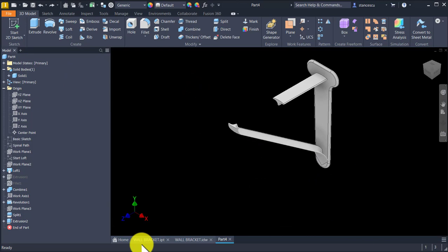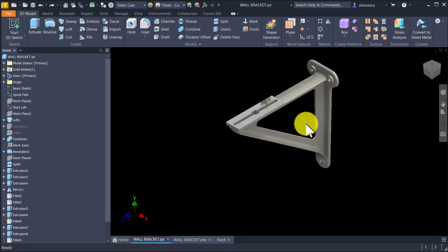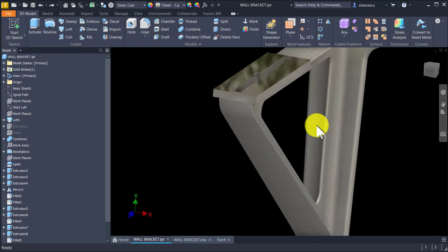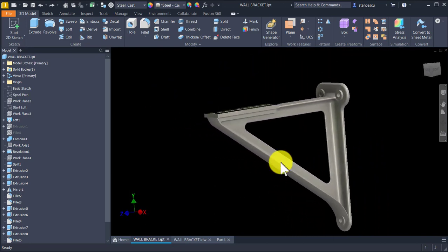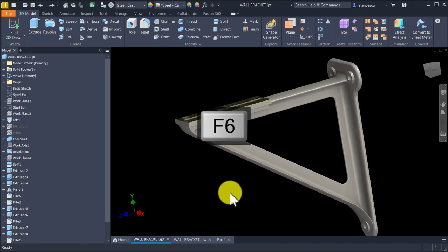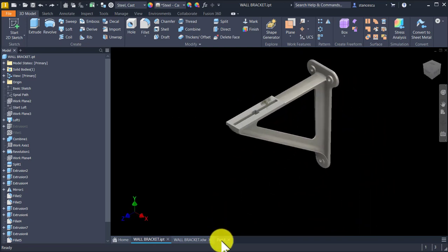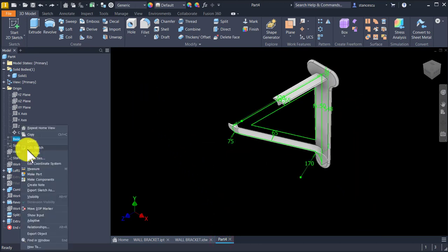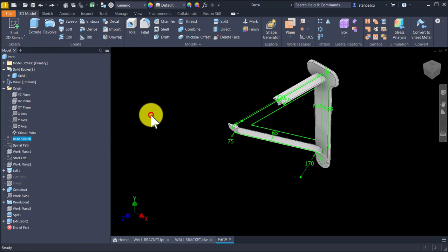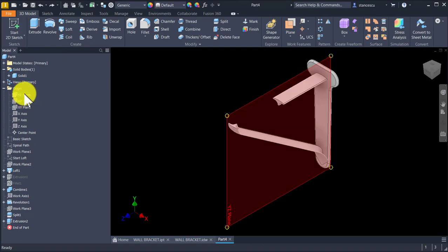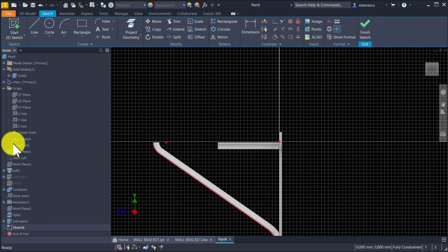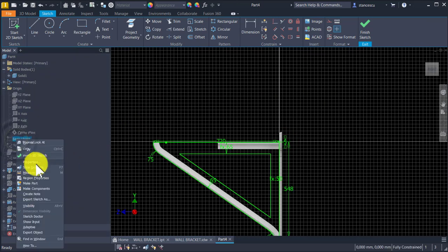Now I want to create this mid triangle, so that I use the basic sketch to take lines from there. Basic sketch to be visible, but after I select the plane, of course. Plane with a new sketch. Now basic sketch is visible.